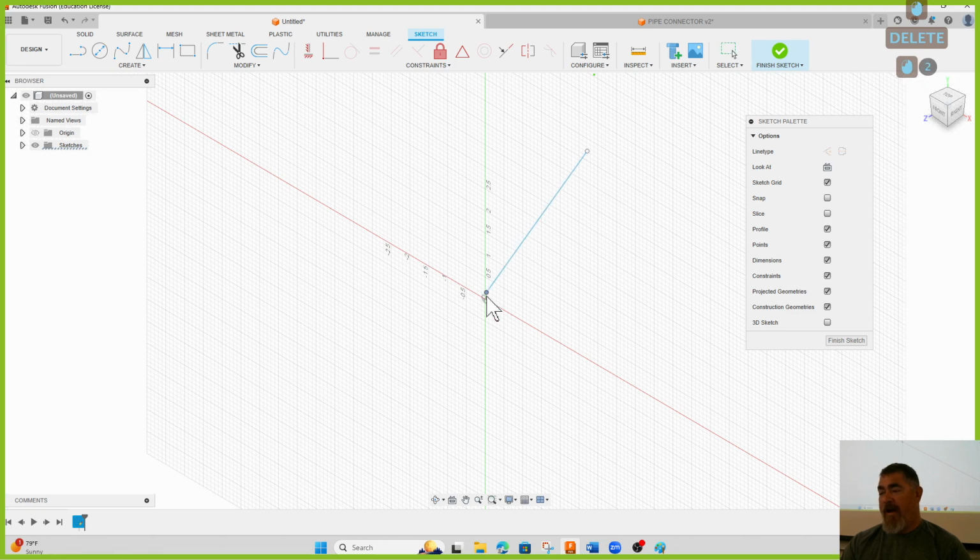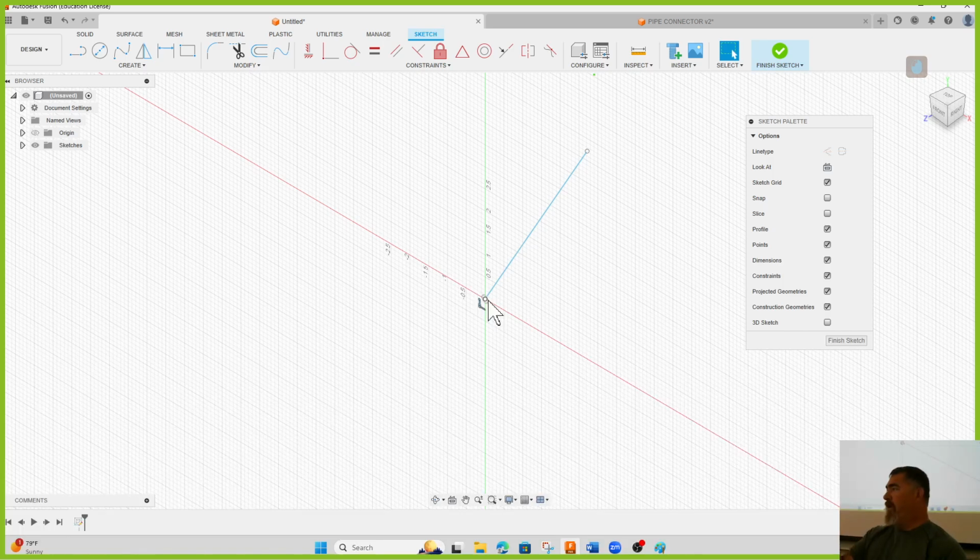If it's here, I can also just drag it to that, and now that adds a coincident. So now it can't move. You can see a coincident runs there now. The same icon. That end of the line is now coincident. It's locked to the origin. If I want to take that away, I can just click on the constraint here, hit delete on the keyboard, and now I can move it around wherever I want.